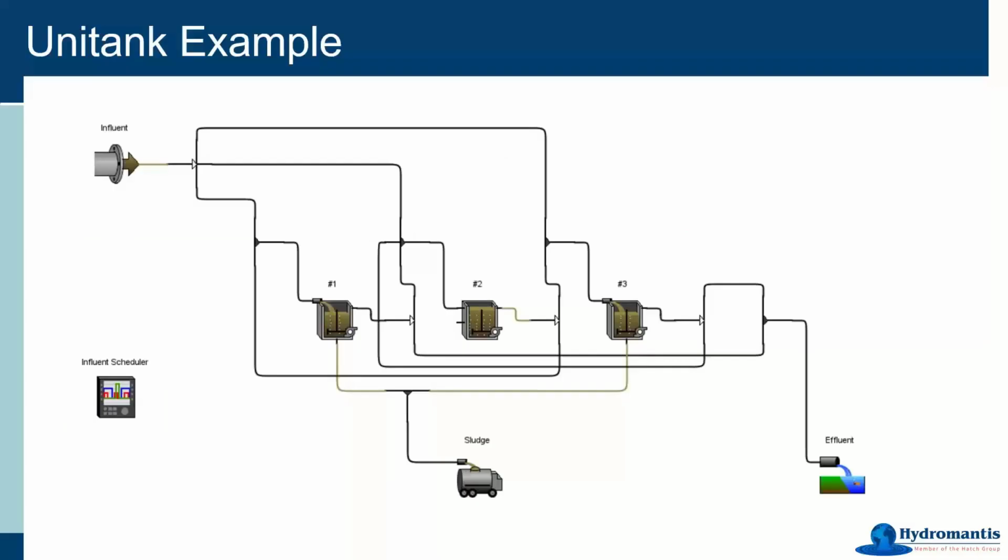So there's a little bit more required than just the usual kind of setup. In this case, we can put 3 of these reactors together and feed to the middle one, and then also feed to the outside one. And you'll notice here the effluent from the middle tank can be fed via the splitter either over into this one, or it can be fed through the splitter this way.